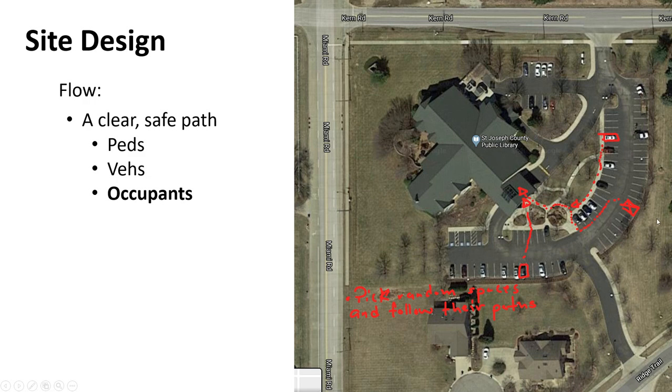So you want to make sure that no matter where you're at, there's a fairly reasonable and safe route to get in from there. And you assume drivers, especially around here, are used to navigating some traffic in the parking lot, right? We're used to going to the big malls and Walmarts, and we'll park out and have to walk through the parking lot in the aisles. And we do it safely, fairly reasonably, quite often. But once we get near the building, we want to have a good dedicated route. So they did a good job on that, I think. So we're taking that into account. And you should be able to point to any parking spot and say, yeah, there is a good, reasonable enough route coming in. That's the idea of flow, where it involves the occupants of vehicles.